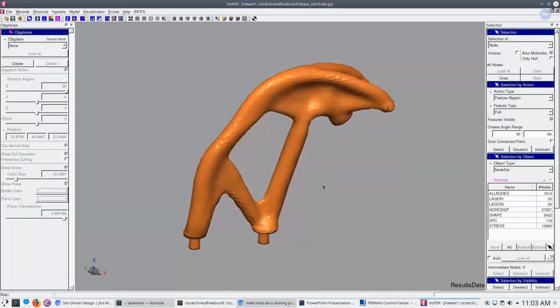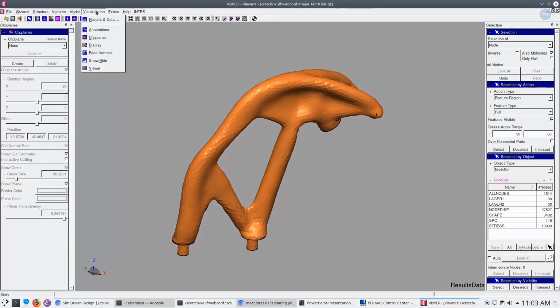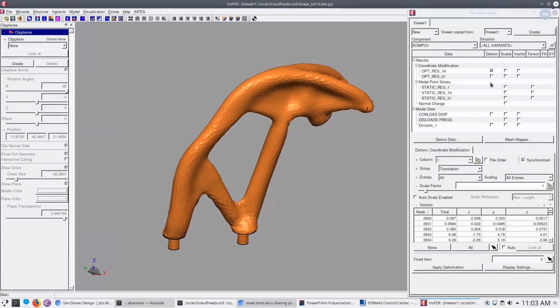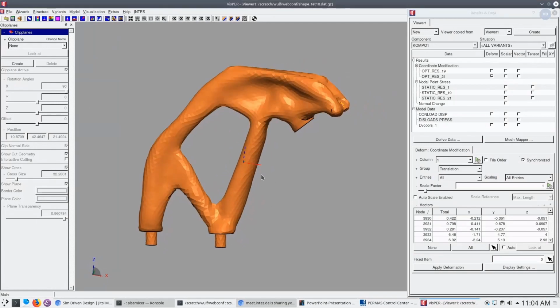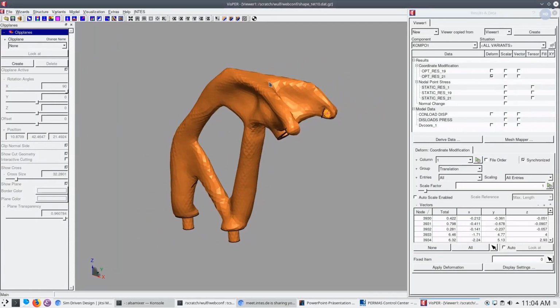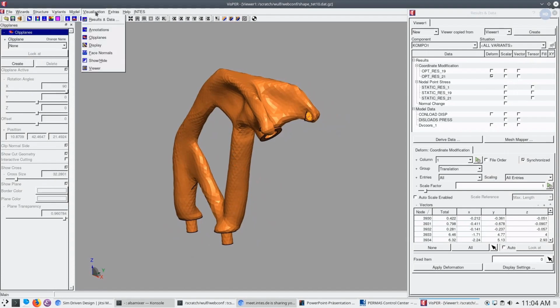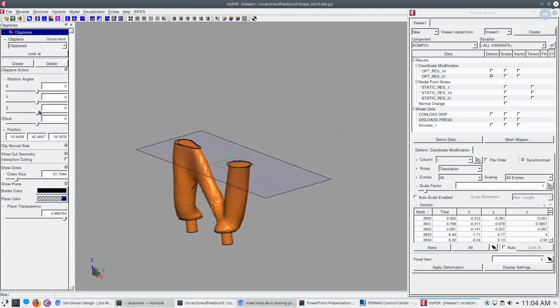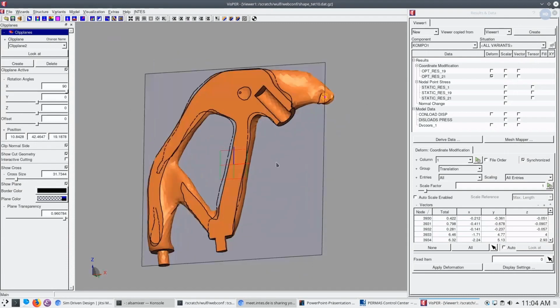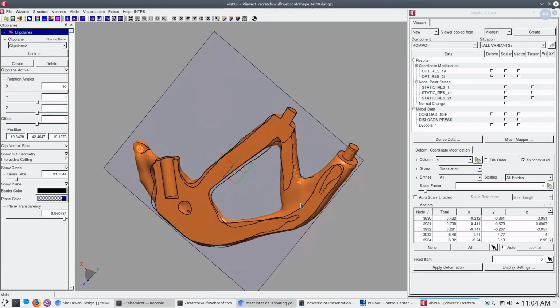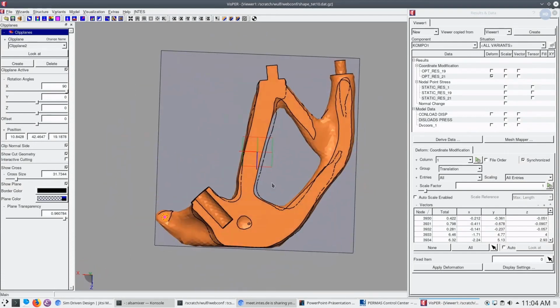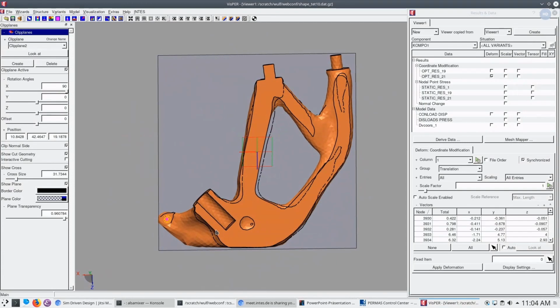Now let's look at the final structure. Go then to the visualization dialog. Just look at the deformation. Now see, to avoid overhang, the need of support structures, this is maintained. Again, just to have a comparison, I do a clip plane in this. There you can see very well. Okay, now change the view of this. So this is the printing direction, printing upwards. Now you see exactly this angle is maintained.